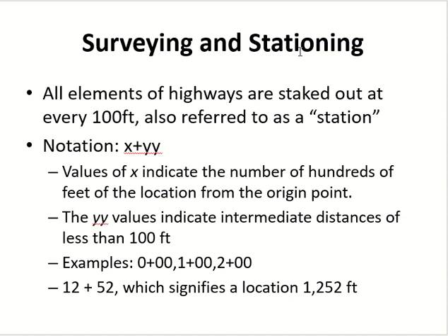That reference point could be the start of the road. It could be some other known point as well. Okay. Any reference point. So, it is represented in this way, okay, with a plus sign. If you are talking about feet, then the number before the plus sign gives you total number of stations, okay, and every station is how many feet? 100, okay.